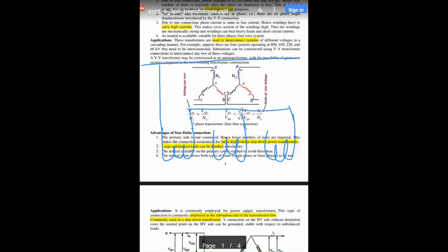These are all connected to the same neutral, and this is the A phase, and all the other terminals are connected to the three different phases like this. So A, B, C, this is the three phase connection diagram of the star system on the primary side. Similarly, we can draw the star-star connection on the secondary side.